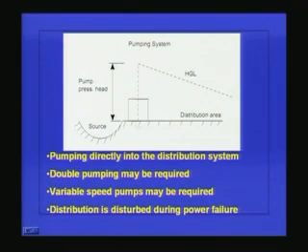In a pure pumping system, we put a pumping plant and a treatment plant very close to the source. There may be dual pumping necessary here. That's one stage of pumping from the source to the treatment plant, and another pumping from the treatment plant directly into the distribution system.